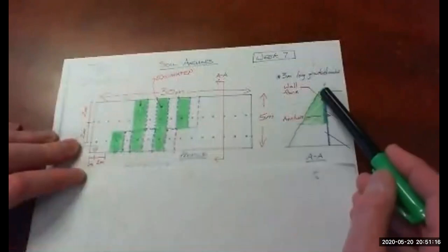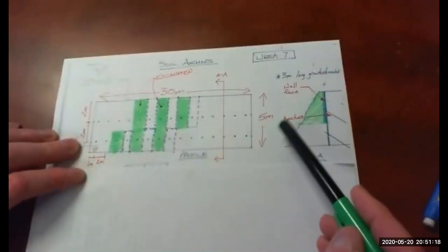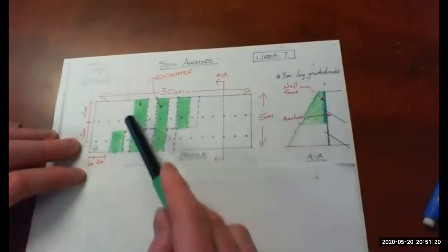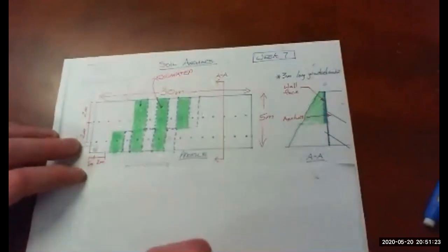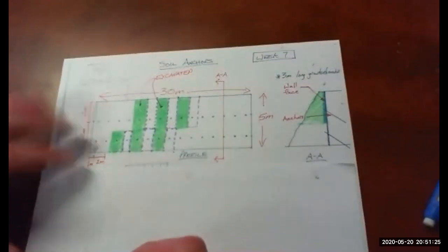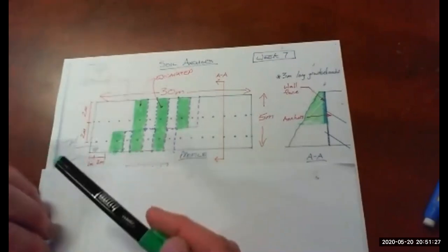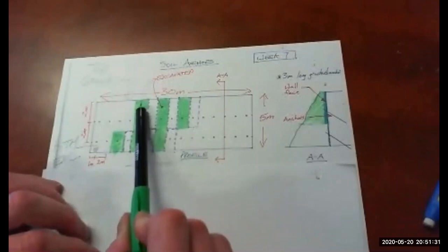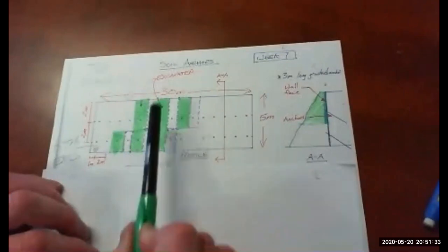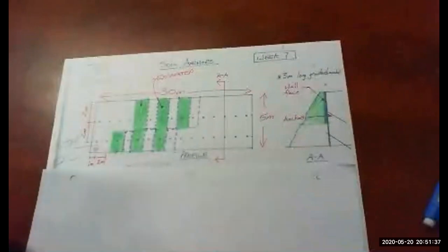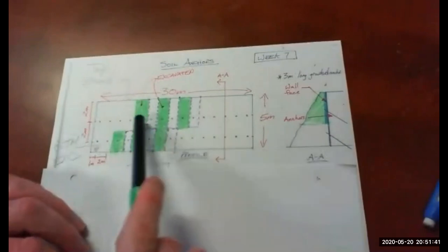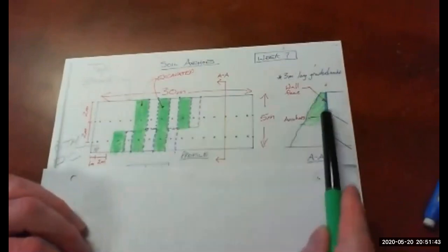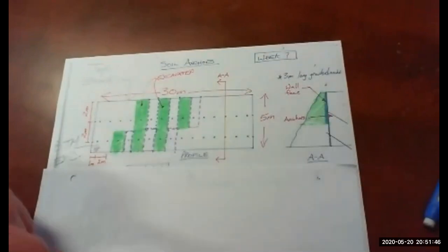So depending on how much of a wedge we left here, maybe you're excavating 10 cubic meters over there. Maybe it's 15. So it's slow work. You excavate 15 cubic meters here, then you do that here and here, and then your excavation crew stops and waits while the shotcrete crew comes in, does the anchors, does the shotcrete facing.